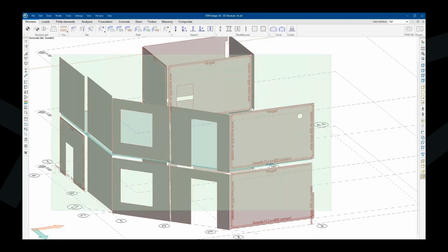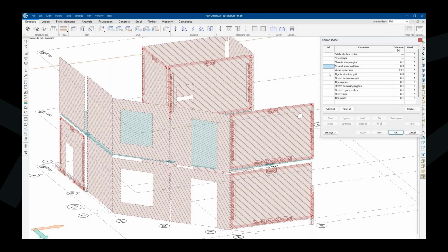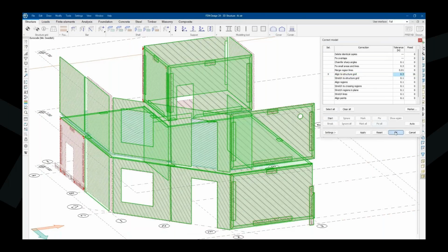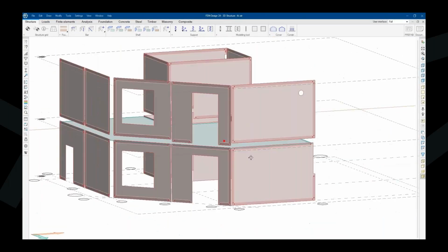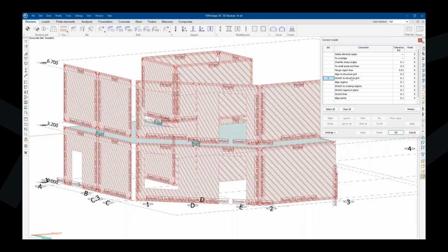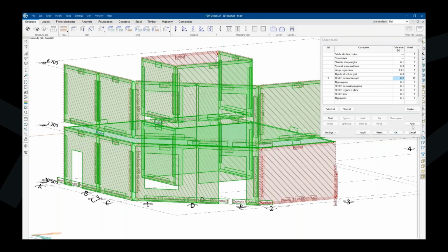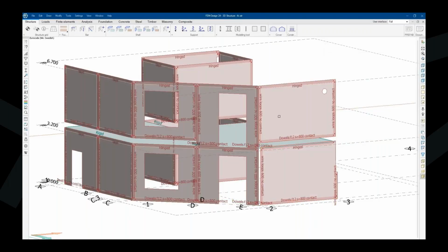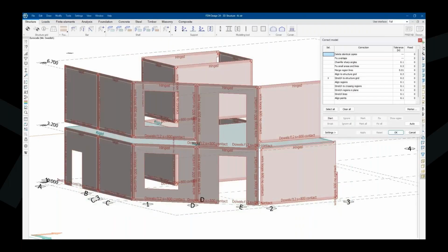The second option or method is to align everything to the plane. So that's what we are doing now. And once we start the operation, everything will be located on those axis planes. So everything is flat now. And the final fixing operation is stretching those corner points of the elements to those axes we have defined previously. If something does not get fixed, usually it's caused by tolerance.